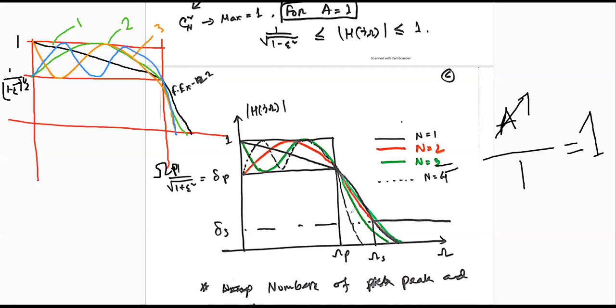When you increase the order of the filter, it will also increase the quality of the filter, in a way that the transition band goes narrow. That is how a higher order filter will give a high number of ripples but a narrow transition band. So you have both the advantage and the disadvantage of the higher order filter. Is everything clear to you?